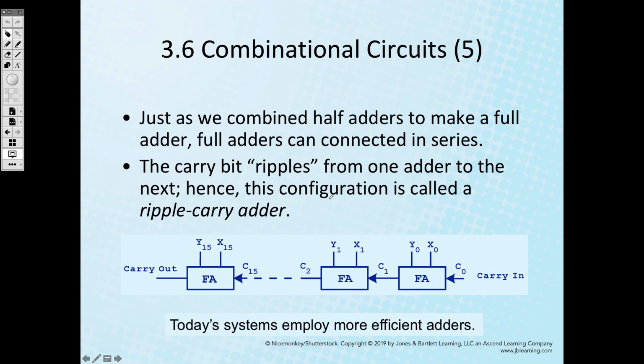This implements a binary number addition with, say, 16 bits. So we have the 16th bit, 15th bit, and so on, down to x1 and x0. Then another number is, again for 16 bits, expressed like this one. When you add those two, you add this bit position and get the sum. But if you have a carry, push the carry to the next position, and with the carry we add those 3 bits, and that becomes the sum for this position, and so on.